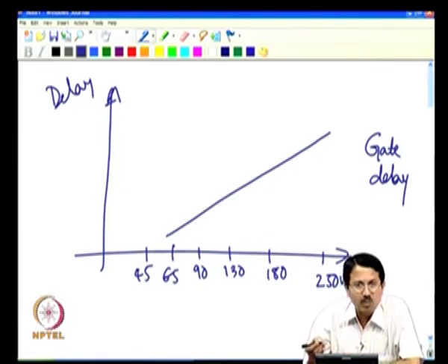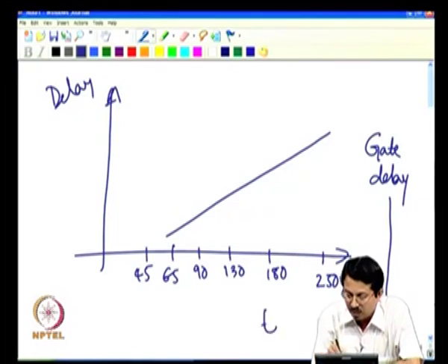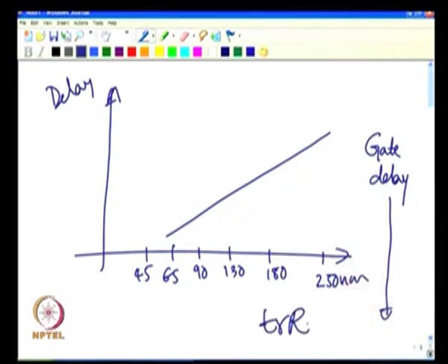You build any gate, it could be a NOT gate, AND gate or what have you, the so called gate delay decreases. Gate delay decreases because gate delay depends on transistors, and transistors become efficient with scaling. Smaller transistors are always better, and the so called CV over I metric becomes better as I start scaling down the transistor.